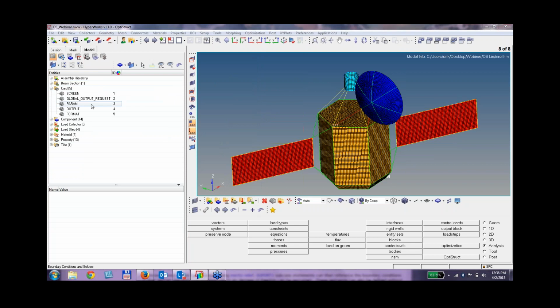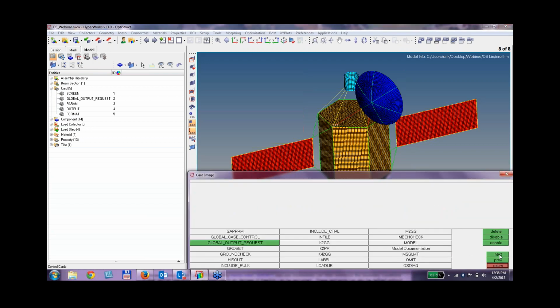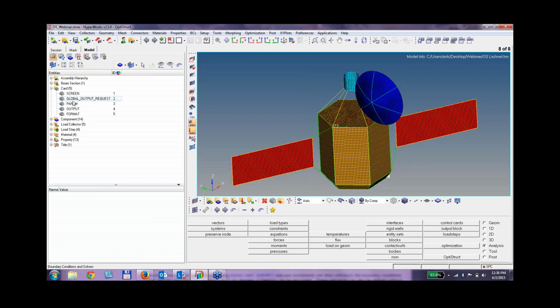It's just simply a matter of establishing the parameter card here. So I can come to my analysis control cards, create my parameter card. And when I have my parameter card in here, I just look down in my parameters for the INREL. I activate that and I give it a value of -1. Your options are 0, which says don't do inertia relief, which is the same as not having it selected. A -1, which is an inertia relief that relies on support constraints being applied.